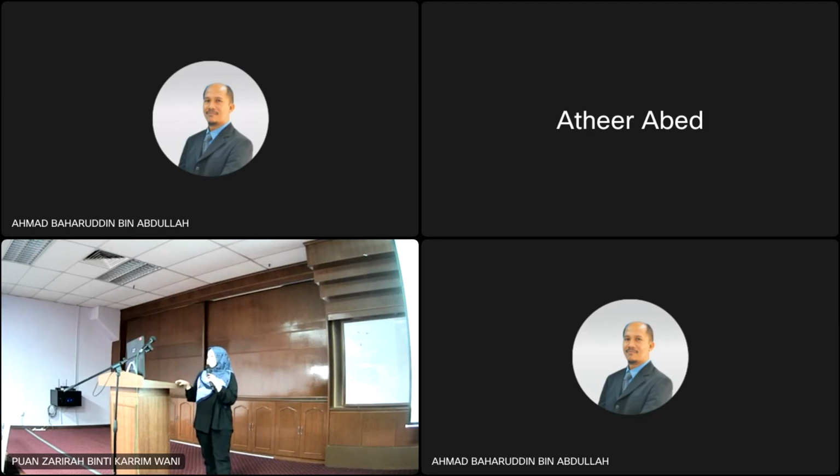Okay, this is the micro hardness analysis. We can see that the highest hardness is found in the B specimen, which is the forged one with the same parameter. Even though that parameter does not really affect the dimensions, it still affects the hardness of those specimens. The highest hardness is in specimen B at the interlayer zone, while the lowest hardness is in specimen C, which is the not same parameter and not forged.